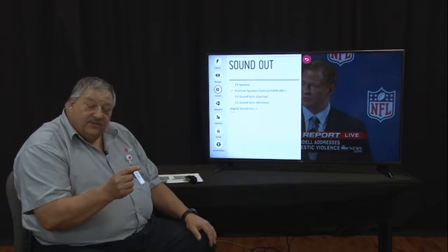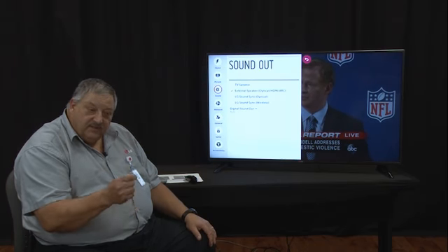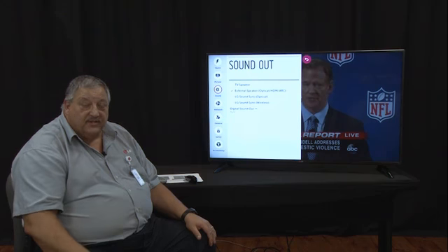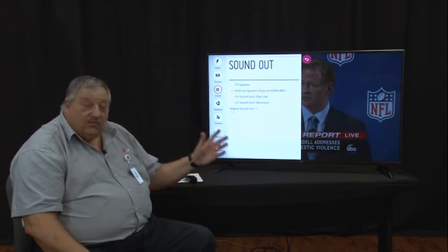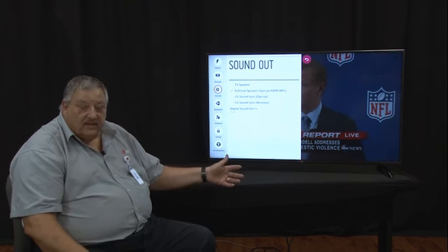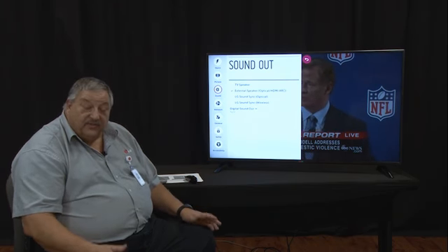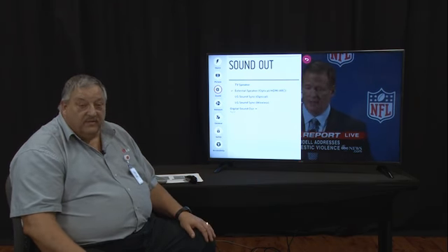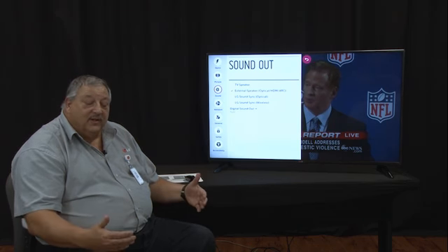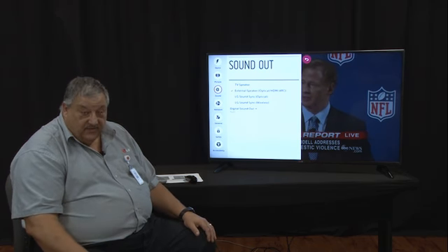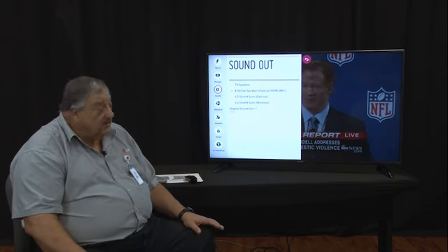The handshake that took place when you first turned on the TV and connected with the digital source through HDMI told it that it wanted PCM, so that's what comes out. But what if a customer has a nice surround system and they want Dolby Digital, the output to a surround sound system, 5.1 Dolby Digital or something?